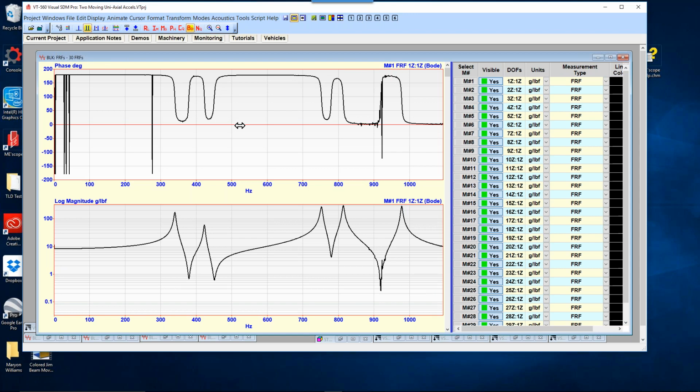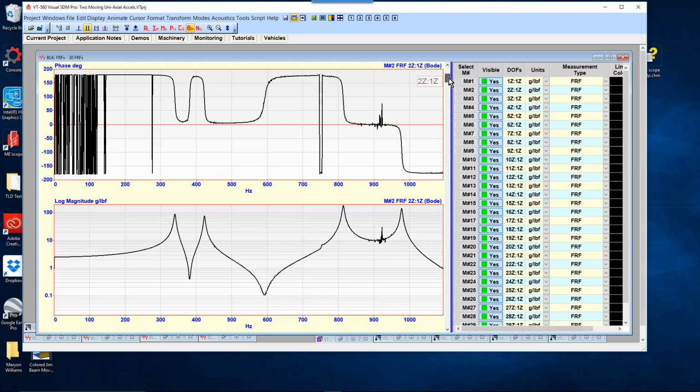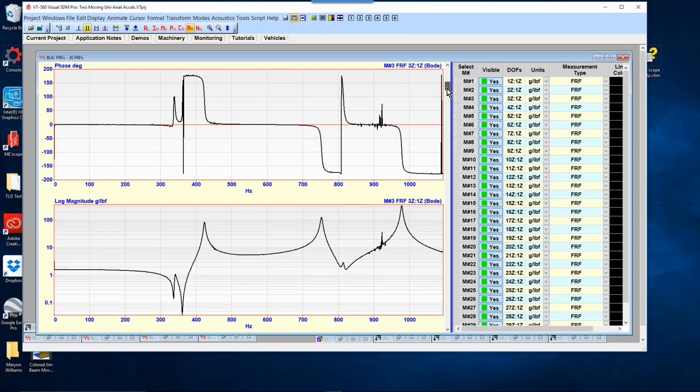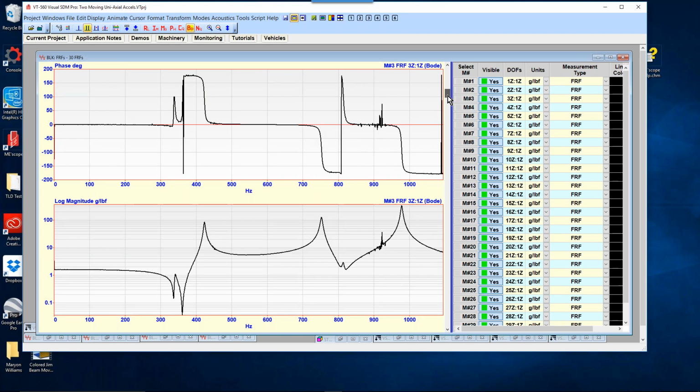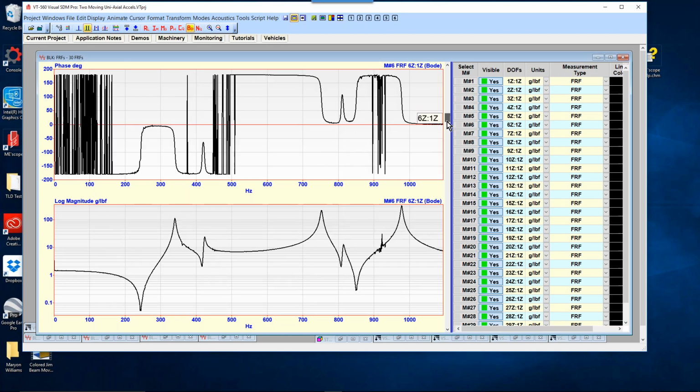You can see, very characteristic of a driving point. We got a little bit of noise here due to the fact that we process random data to get that, and that noise, because of our seed, is going to propagate through all of our measurements. You can see there's a little noise here in this FRF because we're multiplying each of the transmissibilities by the seed, and then creating the next FRF, multiplying that by another transmissibility, and so forth.